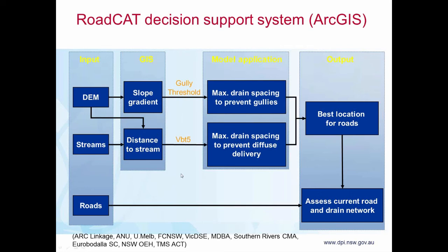Overlaid on all of this, of course, is that original guideline of what are the best drain spacings to reduce erosion of the road surface itself. But effectively, putting all of that together, we can come up with some risk maps across the landscape that show us where are the best places to locate roads and where should the drains be placed.